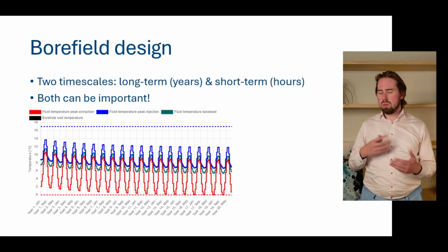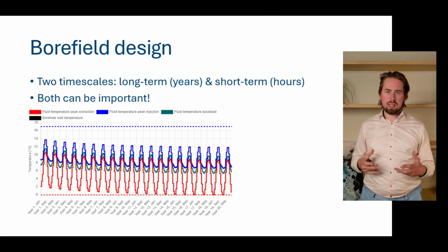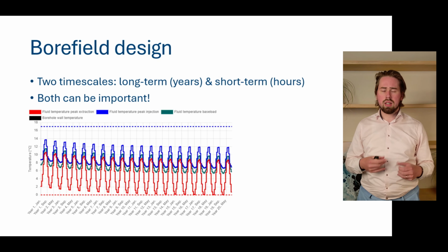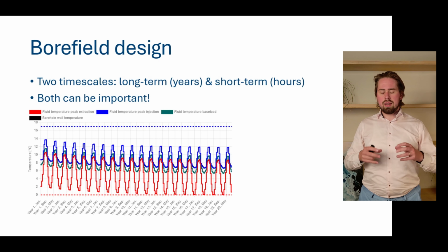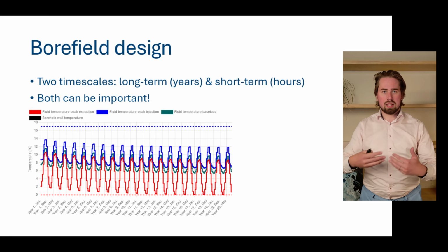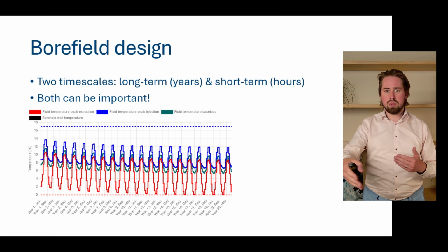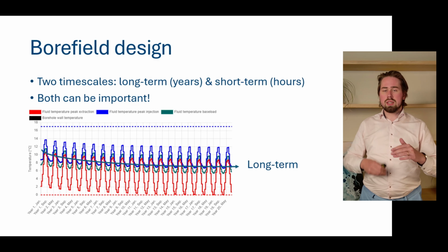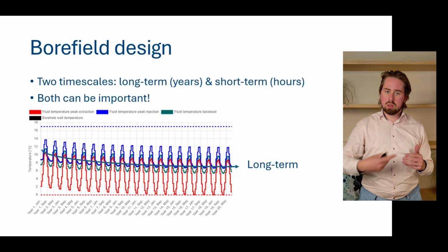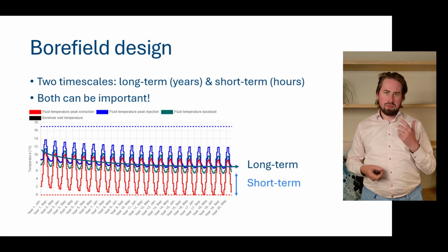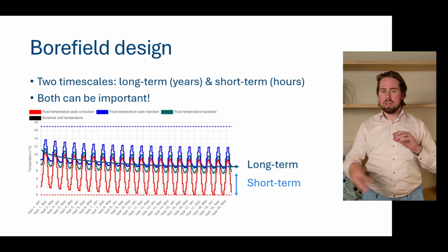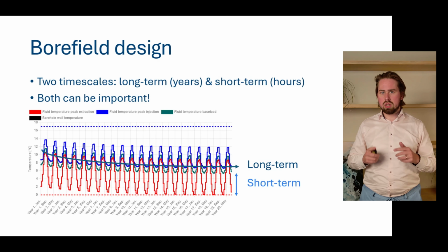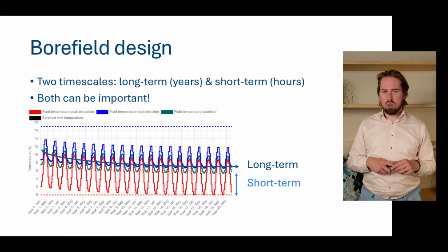And there are basically two ways to look at it. We already said that borefield design has both long-term effects and short-term effects, and we talked about this extensively in part 2. Although imbalance is something that we see after a couple of years, both the short and the long term are important here. The long term is indeed the downward-going trend, as we discussed, and the short term is the difference between our fluid temperature during peak and our ground temperature. Both play a role, and we will discuss why now, starting with the long term and then the short term.